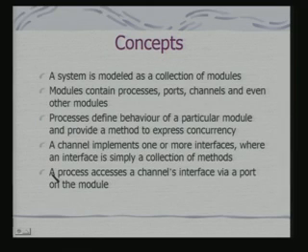So what are the basic concepts involved in SystemC? A system is modeled as a collection of modules, and modules contain processes, ports, channels, and even other modules. Okay? Processes define the behavior of a particular module and provide a method to express concurrency. Okay? A channel implements one or more interfaces, where an interface is simply a collection of methods. A process accesses a channel's interface via a port on the module.